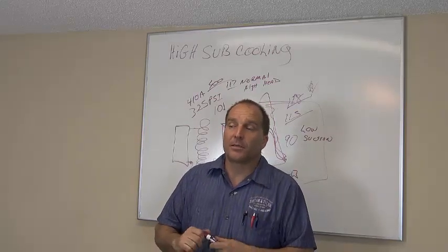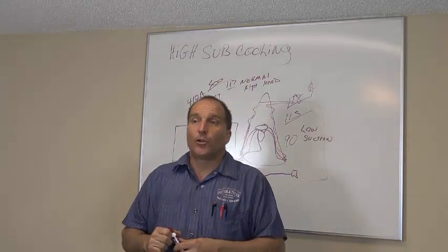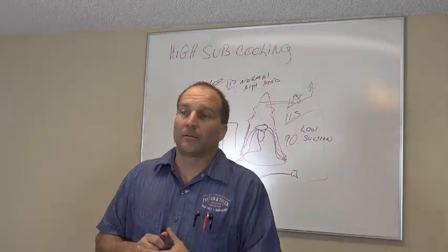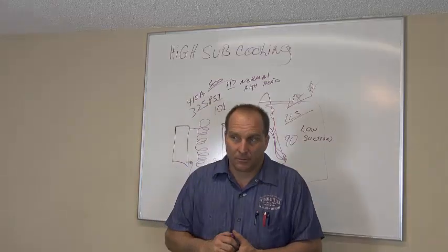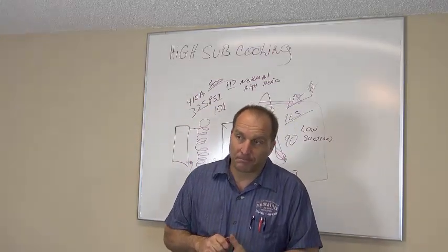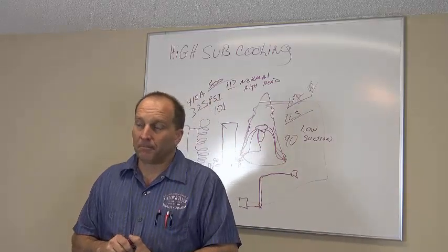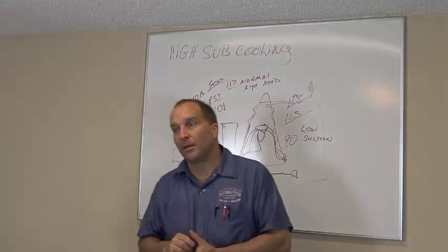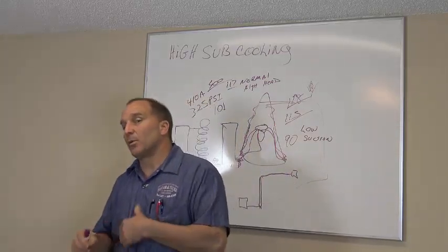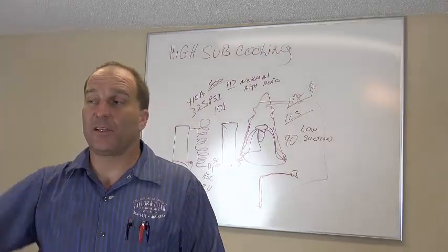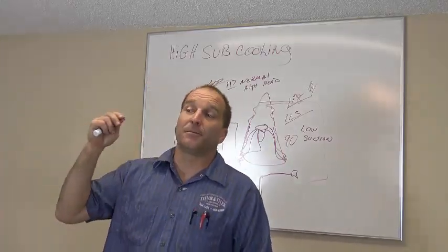What if you got too big of a high side line? Too big of a high side? Mm-hmm. It's going to be low too. It's going to be pushing more down and up. It can cause you a low head pressure, okay? And it can affect your subcooling, but when you're charging the system, mainly it means what kind of TXV do you have? Or what kind of metering device do you have?